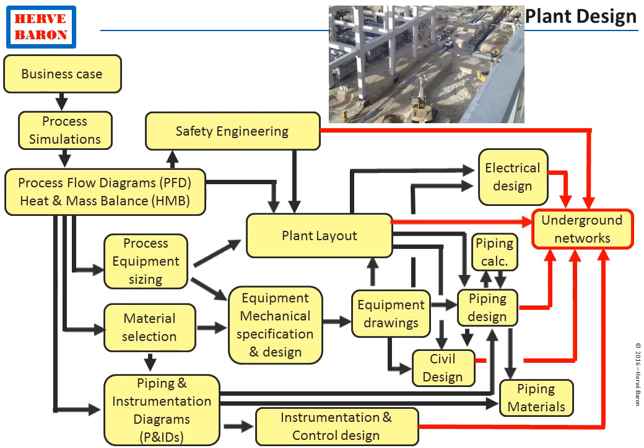Another priority of the design work that is often neglected is to focus on the underground networks. Indeed, underground networks are installed at site before any above-ground networks. Indeed, as you can see on the picture, the equipment, the cranes and so on to install equipment and pipes cannot access the area before the underground networks are installed and the area is backfilled.